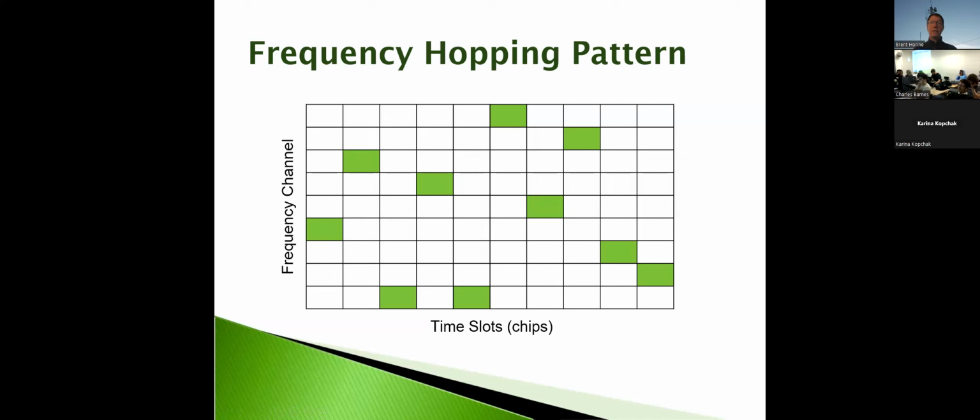And so for fast hopping, you would transmit a single symbol, and it might take several of these hops, right? And so you would need to step your synthesizer to these different frequencies, measure the energy content in the different ways that we demodulate an FSK symbol, and then add all these up, right?